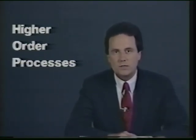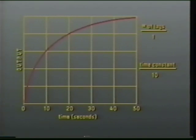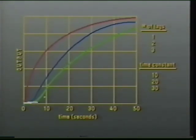In most situations, higher order lags are represented as a region of dead time, followed by a first order lag. For example, we see the first order lag in this graph with no dead time apparent. Now we plot the curve of the second order process and see that the first portion of the curve is horizontal, indicating a dead time. The third order process curve has a different shape and different values, but it still can be characterized as a region of dead time followed by a first order lag.